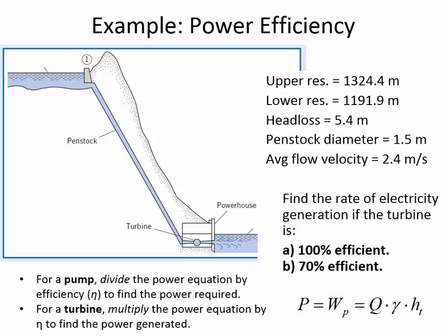And so you can find out the H sub P by those things. The elevation difference and the losses tell you the H sub P, and then you'd put in the flow rate, the unit weight, and multiply it by the pump head. So then that would tell you, without any losses, how much energy is needed to lift the water uphill.